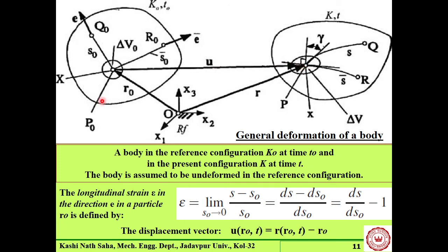And how will we measure shear strain for the line P0R0? Again we have to track that line. This is the line PR, this is PQ, and at that point we will construct tangents to PQ and PR. Is this clear? So again, on this tangent line, let us construct a perpendicular. With this perpendicular shown, this is our shear strain gamma. Understand?